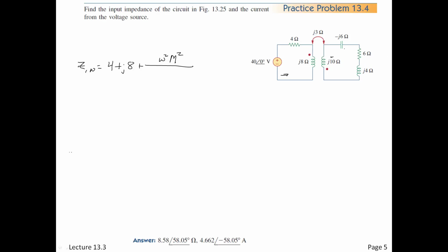I go over here, by the way, to keep this easy and looking like the past. I'm going to combine this with this into something that's minus j2. And this guy will be our R2. Okay, so it looks like the inverses from before. So we will have 6 plus j10, and then minus j2, this is the load, right? I'm calling that Z of the load.